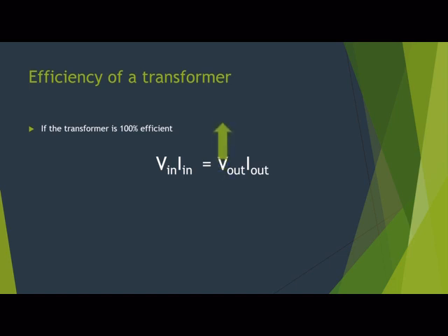If the voltage at the secondary becomes higher compared to voltage in primary, the current in the secondary will become lower compared to current in primary. This is the trade-off which a transformer has to make in order to step up or step down.